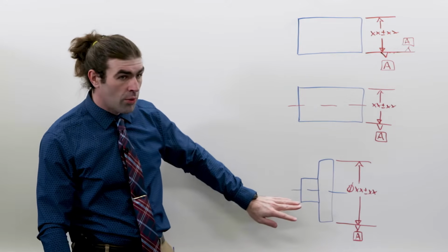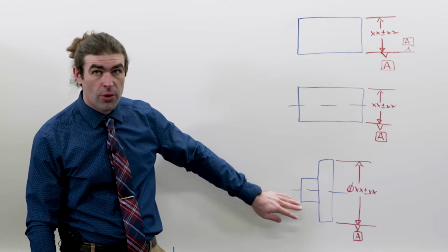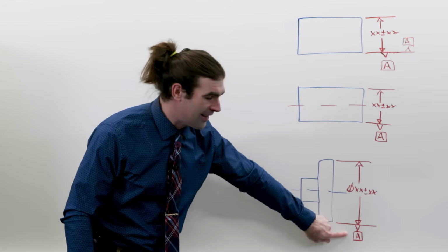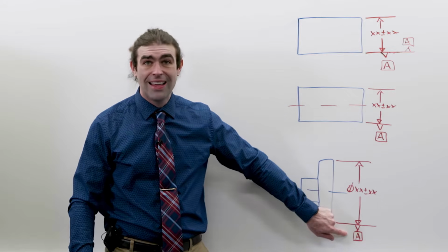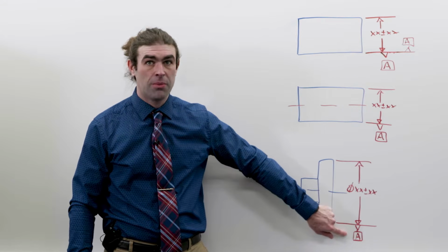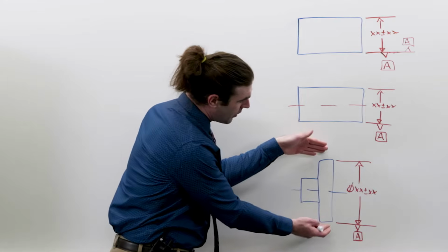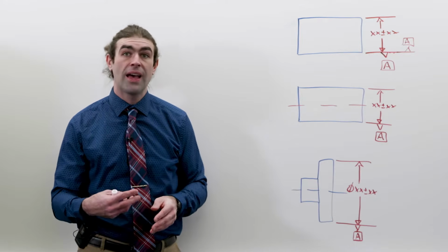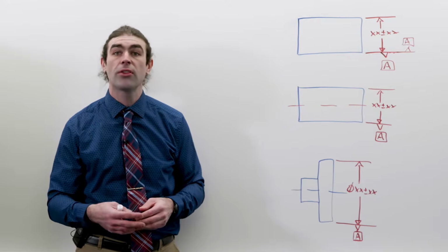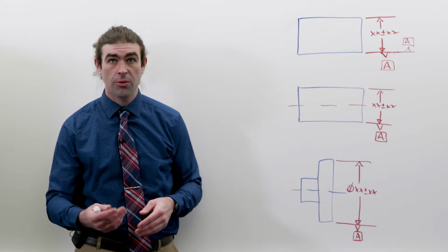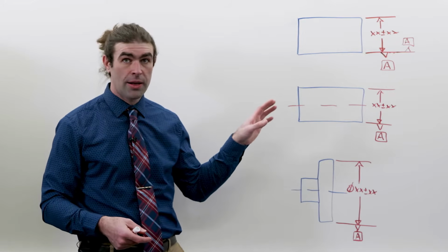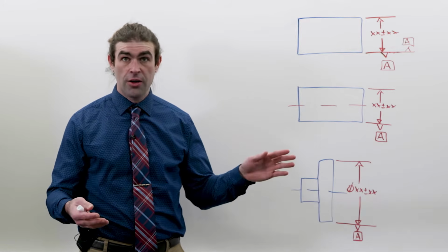Next up, when a datum is a cylinder, so I have 2 diameters here, one of which has a plus or minus dimension and the datum feature symbol in line with the dimension. That means the axis of this diameter is the datum. You're comparing the axis of any other diameters to that diameter. Okay? Now, you often have feature control frames on your datum features.